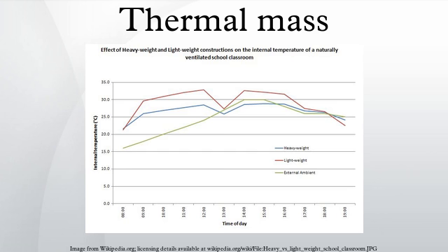Scientifically, thermal mass is equivalent to thermal capacitance or heat capacity, the ability of a body to store thermal energy. It is typically referred to by the symbol Cth and measured in units of joules per degree Celsius or joules per Kelvin. Thermal mass may also be used for bodies of water, machines or machine parts, living things, or any other structure or body in engineering or biology. In those contexts, the term heat capacity is typically used instead.